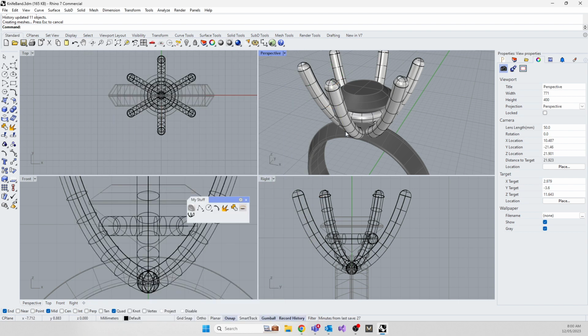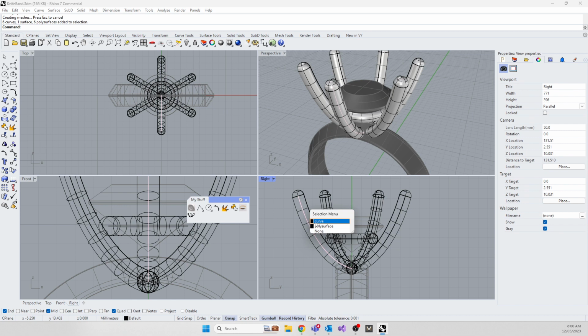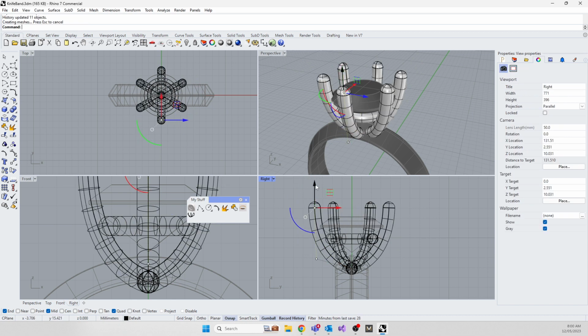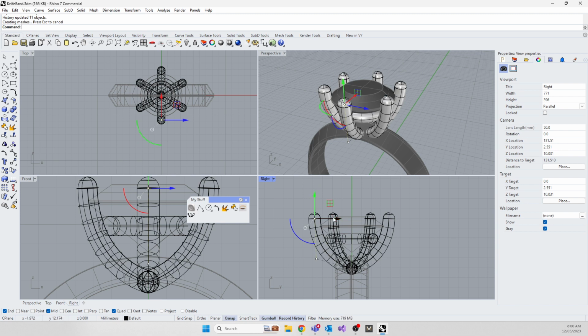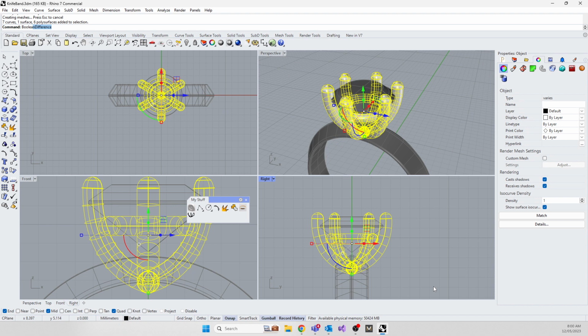And they are already joined together? No, once you join them, all your history is gone. If you take these things and you Boolean them, so let's go, where's my curve? Did I delete my curve? There we go. That's why you save it now, before you do that. If we bring that in and they're all touching and you go Boolean union, and they are now together, so Boolean union.